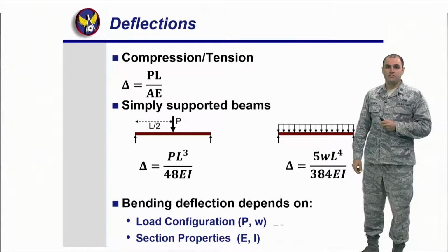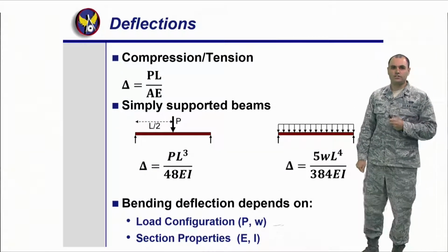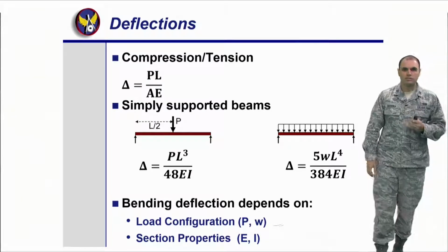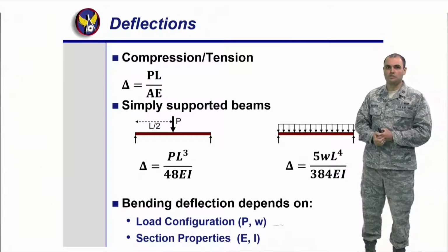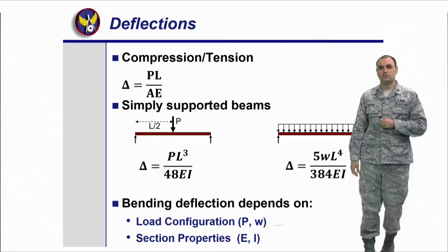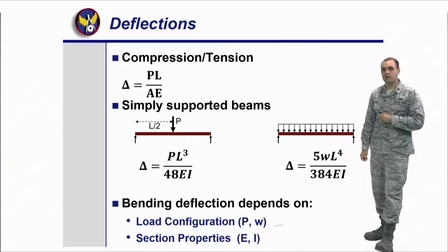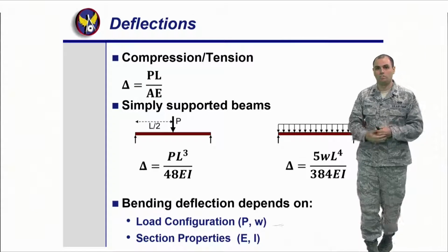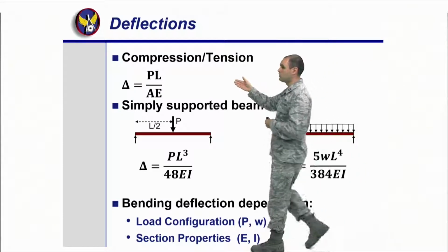Another one is deflections. So we have compression and tension deflections. Yes, in both ways. But mostly we're going to talk about compression. It's usually the easiest one to talk about. But remember, tension, if I have a rod and I pull it out, if I exceed that strength, it's going to start deflecting and extending beyond its original length. That's why I talk about strain, and also in this case, the delta, which you're going to calculate, is based on the properties. So look at it. It's based on the material properties.